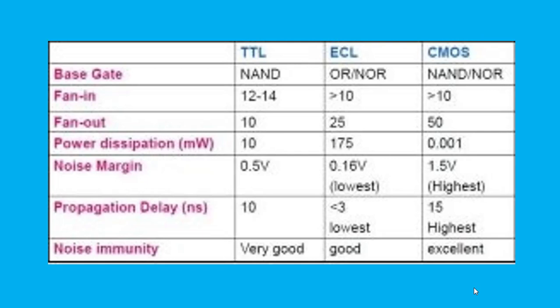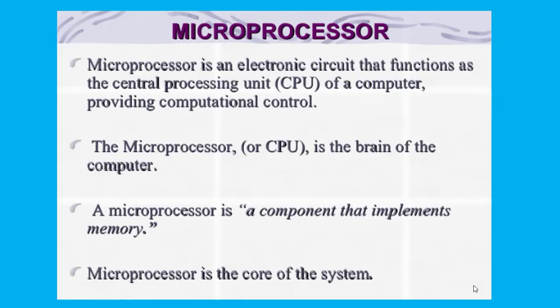Each differs from the other in the type of circuitry used to provide the desired logic operation. While TTL, ECL, and IIL use bipolar transistors as their main circuit elements, MOS and CMOS use MOSFETs as their main circuit elements. These technologies are also called logic families. Several subfamilies of these main logic families are also available.